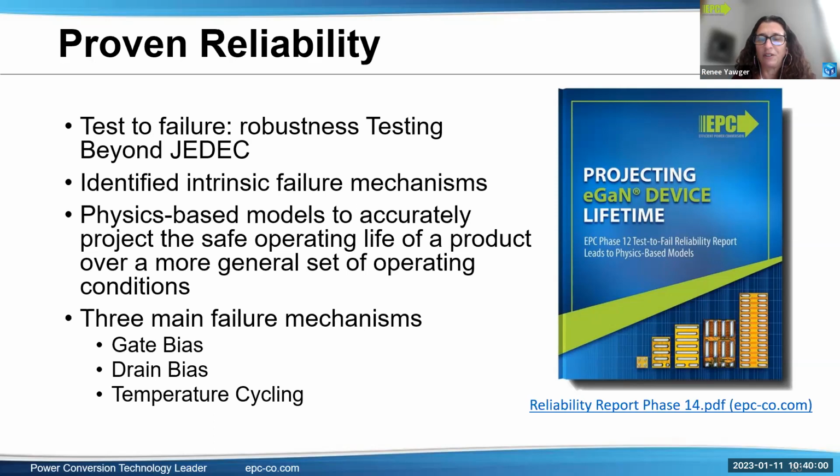Okay. What is your solution for huge EMI? The solution for huge EMI is, don't have huge EMI. I think that's the solution. So, EMI is a difficult topic. It is very much related to not just how fast the device is switching, but all the parasitics that are linked to that switching.